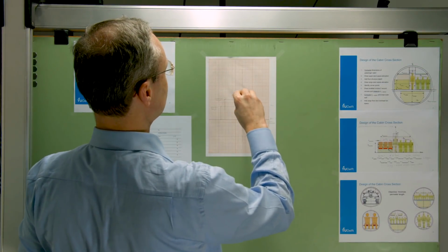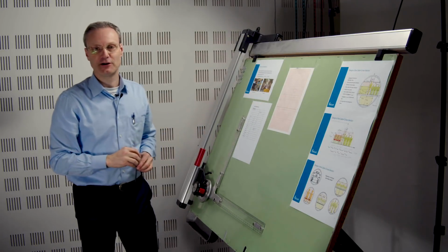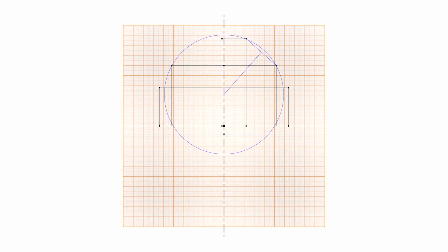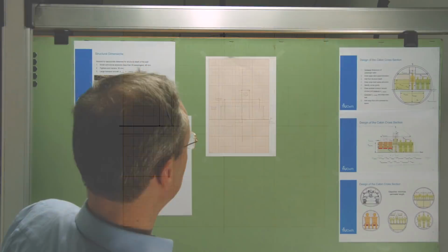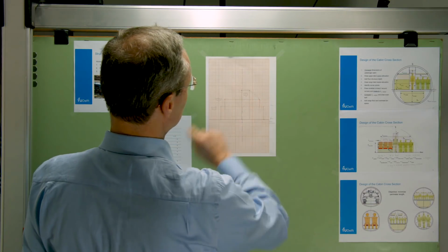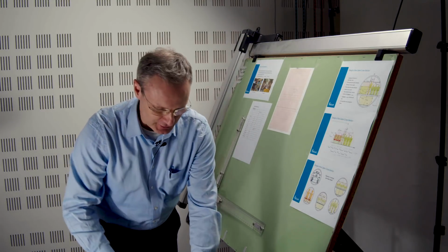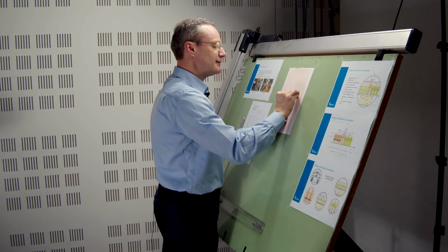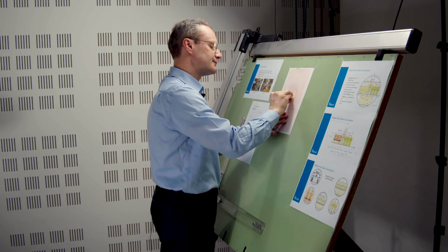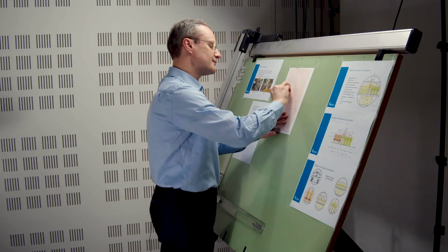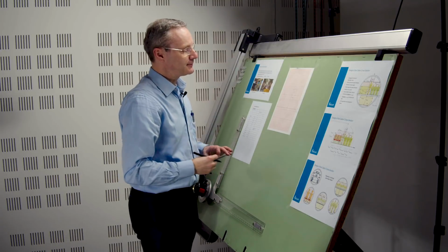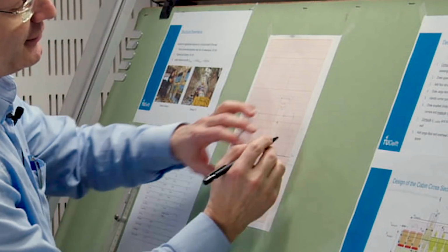And then again, you see you have immediately a problem. What's wrong here? Well, what's wrong here is that you now aim at this highest point, but the width of this whole row of seats is probably more limiting. So you need to probably aim for this point and this point, or this point and this point. So let's do so. Again, remove the line here. You can also remove the auxiliary line. And let's apply the trick again. Let's say, okay, now expect that these 2 points will be limiting.